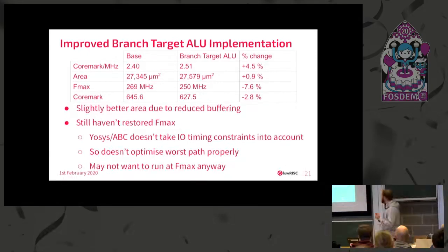And then the other thing is, this is a microcontroller. You're not necessarily wanting to run it at the maximum possible frequency. But it is important that we don't just keep adding things that keep slowing it down and slowing it down. So overall, probably a pretty good optimization. For someone who really wants to run Ibex at the maximum frequency, they can maybe want to turn it off, but they can do that because it's a configurable option.